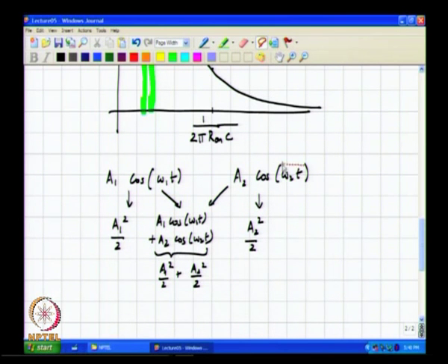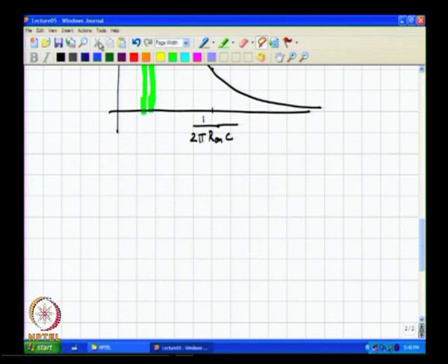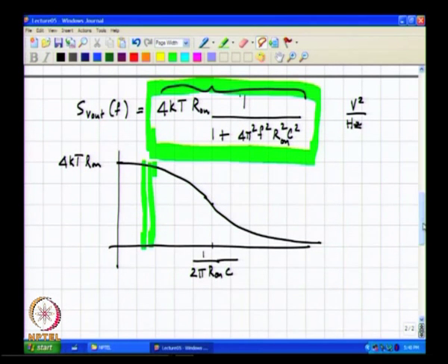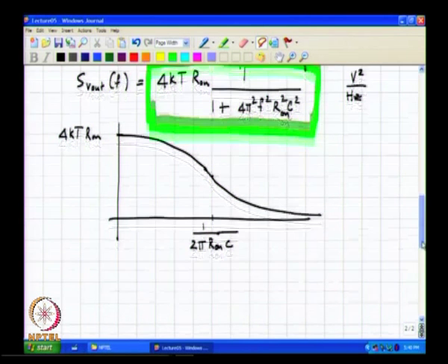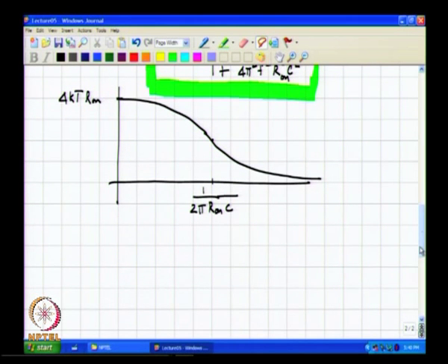So even though a lot of you said simply you can add up the powers, that is only possible because all these different tones are at different frequencies. Now therefore the mean square value of the waveform at the output of the filter can simply be gotten by adding the powers in each infinitesimal bandwidth.